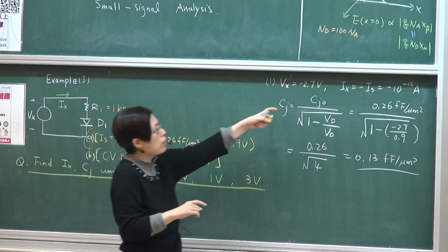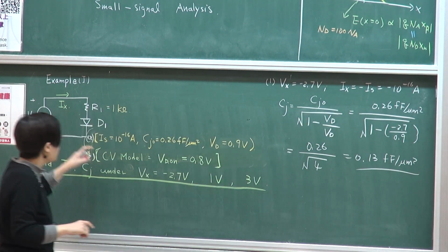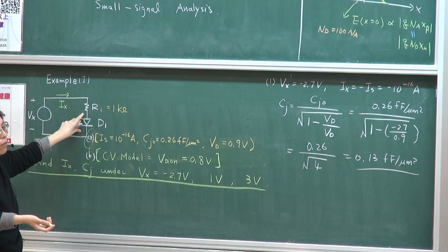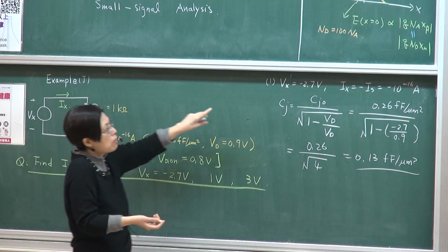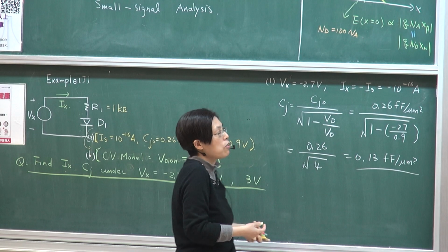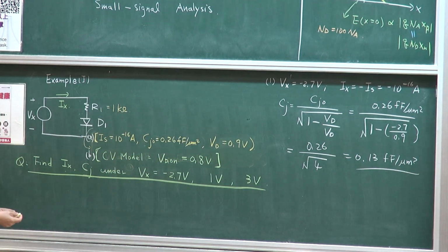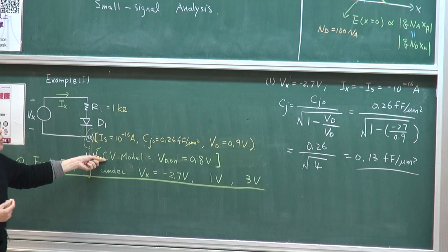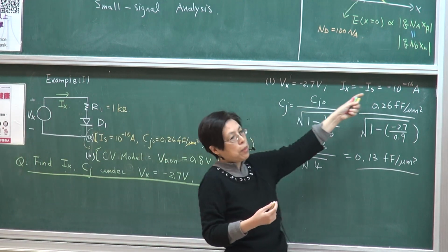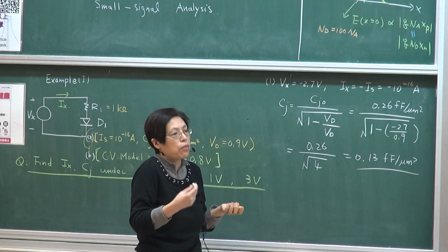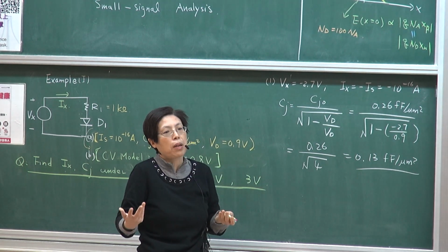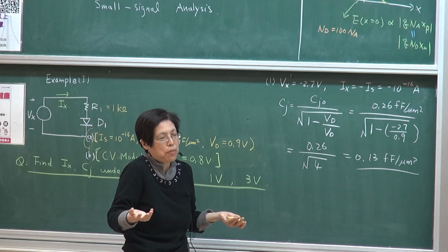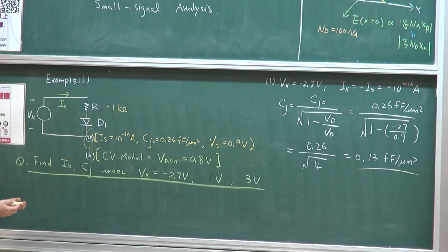There's essentially no current. You don't need to consider voltage drop across here. It doesn't make any sense. And the current is in reverse saturation. Therefore, it's minus Is. It does not change too much. Okay? And the constant voltage model doesn't work here. If you're using the constant voltage model, this Is will simply be 0. But you don't actually care, because whether you give me the number 0 or 10 to the minus 16, it's essentially the same for most circuit considerations. Okay?